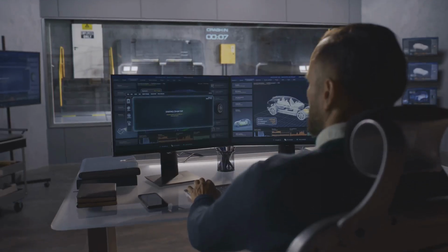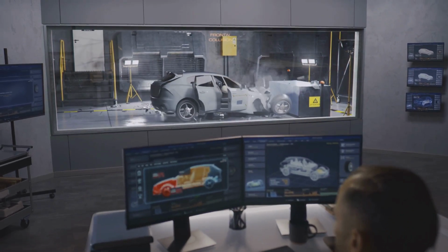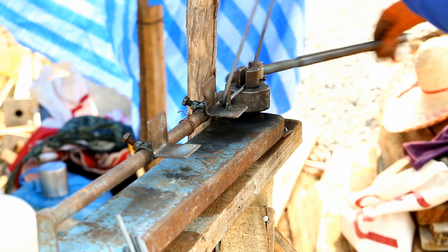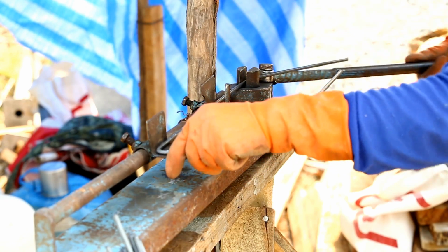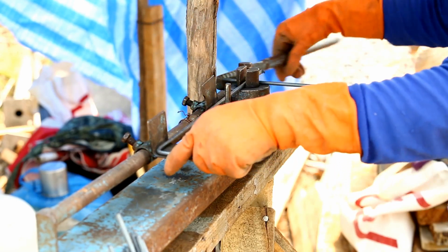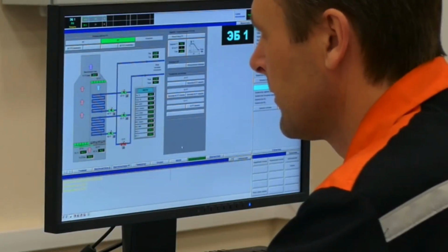Traditional methods might look at overall stress, but strain life delves into the local strain conditions. It acknowledges that even if the bulk of a structure is under low stress, these tiny localized regions can be experiencing much higher strains, especially when plastic deformation, a permanent change in shape, occurs. This detailed view is what makes the method so powerful.